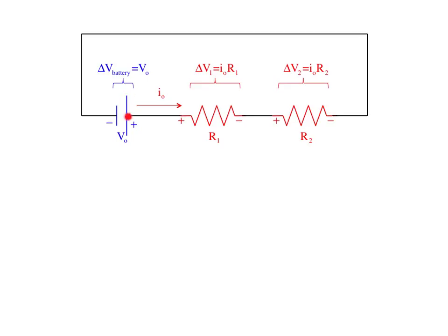The positive terminal of a battery is positive because of the way the battery is built. It's inherent. It's an inherent part of the battery. The positive side of a resistor is identified by the direction of the current flow. Current flows from high voltage to low. So if the current's flowing in this direction, this is the high voltage side and this is the low. If the current was flowing in this direction, this would be the high voltage with this the low.